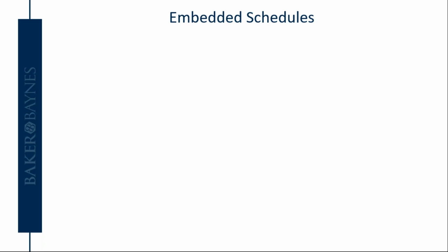So I didn't talk about quantity or building component schedules, you would have noticed, because that's the one that people use most often. What I do want to talk about is embedded schedules and key schedules, which are both a type of quantity schedule. So embedded schedules, it's basically when you put one schedule inside of another schedule, right? The one schedule is embedded in the other one. But what's specific about this one is that it can only be used with rooms, spaces, and system schedules.